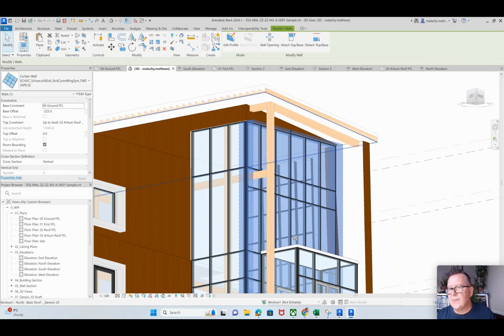Okay, so we do need some support here for those joists that I've got in there. And we could always turn some joists and come this way as well. It's not too difficult to sort. I just need a bit of support for it. But if I take that column out then and I join those two, I could nearly cantilever that because they're not taking a huge amount of weight in one sense.